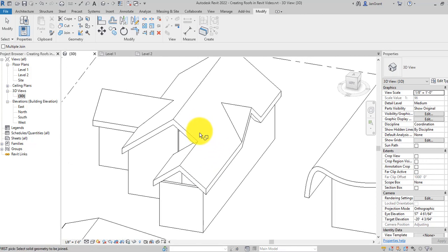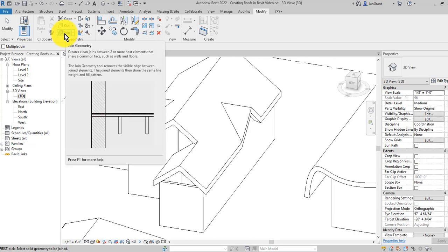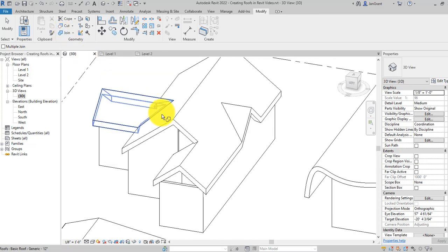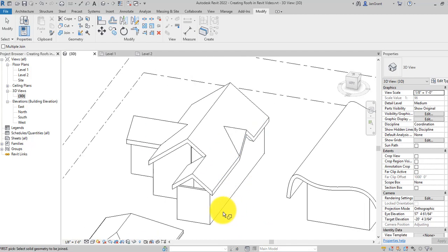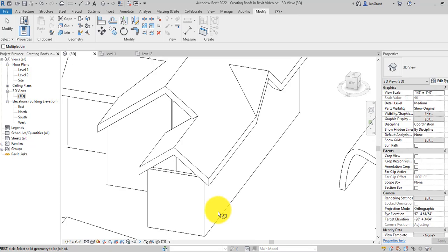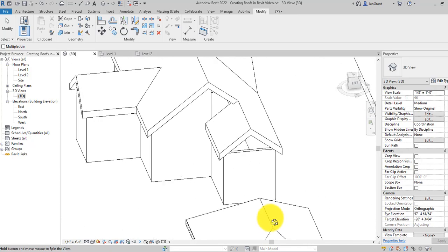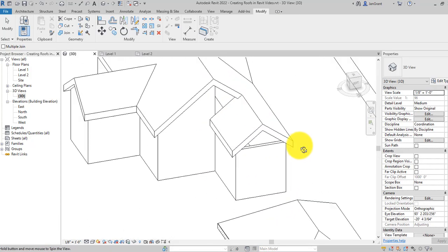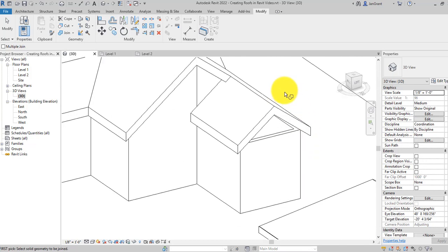And this is exactly what you can use if you happen to have a roof like this one that's going into the other roof and you don't see this line and you want to see the line of the valley there. Use this join and you'll see it. You'll see that it'll define the valley for you, this line right there. Okay, so that's one issue solved, in that you built an addition that's on the end, and that's supposed to be all one roof, so we're using the join to take care of that.